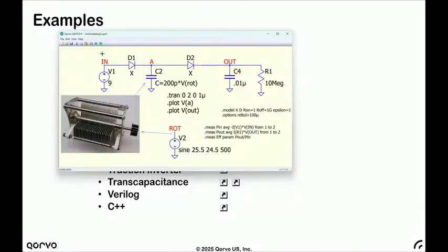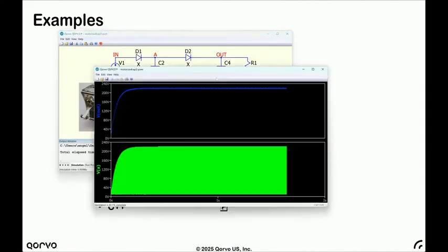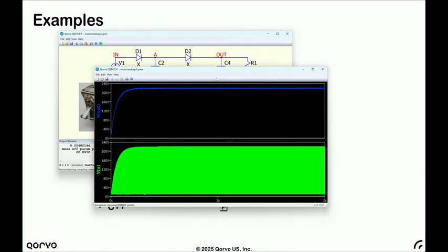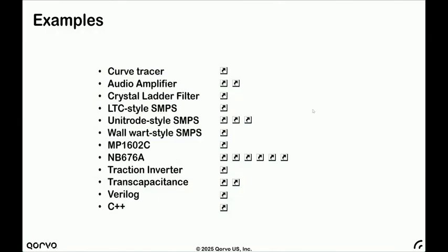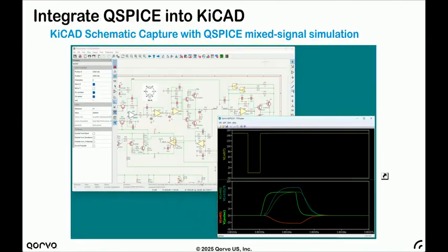Well, this is all based on the idea that you can't conserve charge if you write in terms of capacitances. That's only because you don't integrate the equations correctly. So in QSPICE, I add a corrector step when I'm integrating the differential equations. Here I say the capacitance is based on something, and it conserves charge. That's basically because I've added a corrector step to the integration of the differential equations. That's original to QSPICE. You can buy this from Spectre or HSPICE or wherever. They don't do that. They just don't have that technology. They don't have those numerical methods implemented in it. All right, that's enough of all of that.